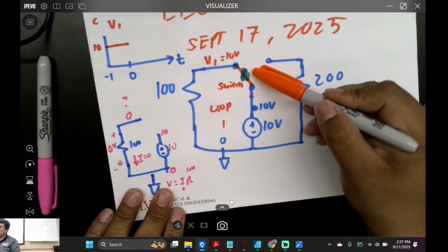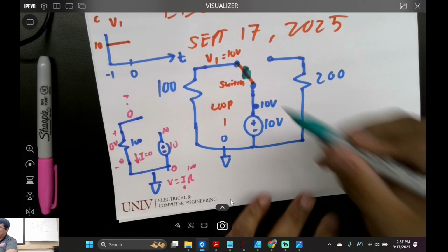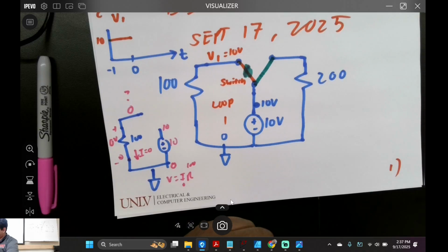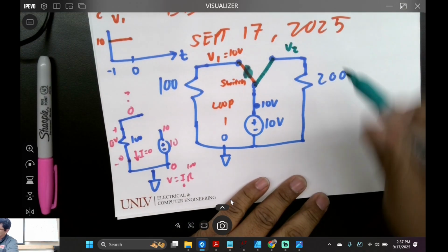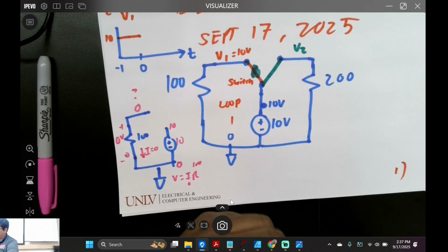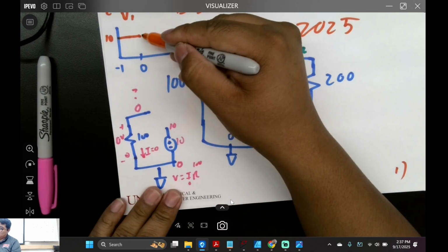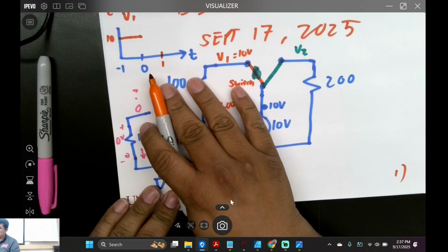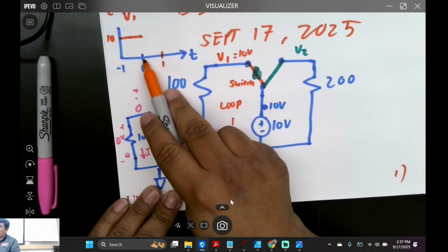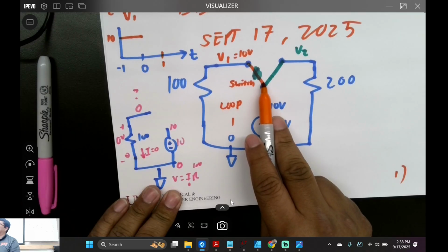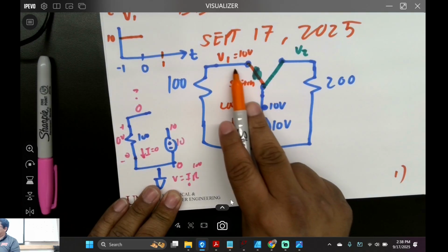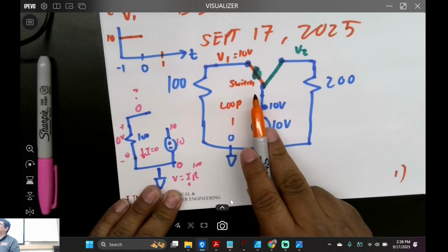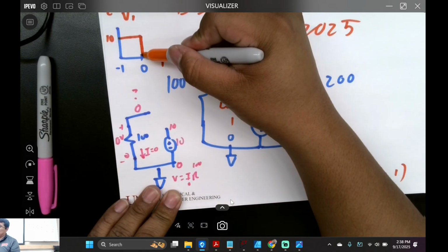Now, we just cut this circuit, right? Now I'm about to do the following. We're going to connect that, okay? I'm going to call this one V2, right? We cut this at, let's just say, time 1, or something like that. I'll just keep that closed. At time 0, I'm gonna cut this circuit, right? Instantaneously, this V1 is gonna go to 0, right? It's gonna go from this 10 volts down to 0. Is that correct? So we should be able to see some type of drop, right?